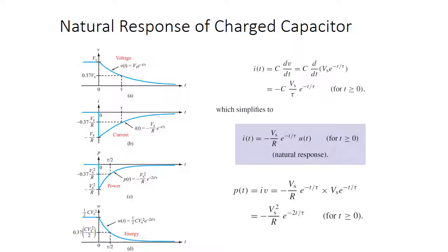That's going to try to throw as much current as possible. The current's going to move really fast through that capacitor, through that resistor. And as the charge gets lower, there's less forcing that current through the resistor, and also there's less voltage, because voltage is pushing on that circuit. So as both of those die, your power is going to die. So if you're going to blow the resistor because you threw too much power through it, that's going to happen immediately when you throw the switch. If that doesn't happen immediately, you're slowly going to get less and less power all the way back to whatever time you're looking at, where there's almost no power being consumed.